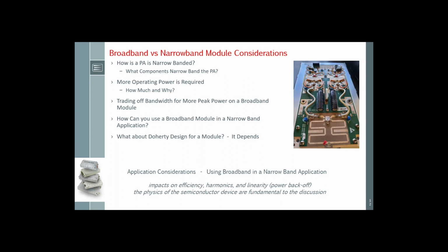So there are some devices that are matched to a certain part of the band, and they derive amplifiers that are narrowband. The other aspect with respect to efficiency is, for example, that you can use Doherty amplifiers, which have the combining transformer at the end that will be narrowband. They have very high efficiency, okay, because part of the device is operating class C. They are very usable for communication, telecommunication or broadcast.